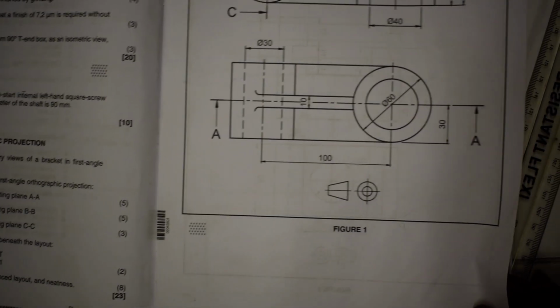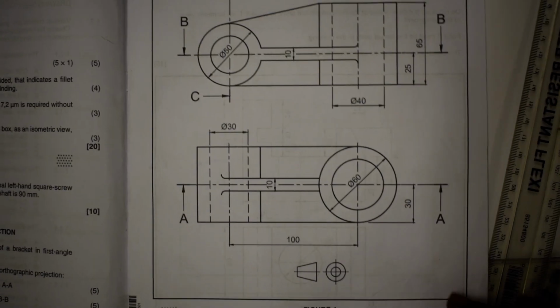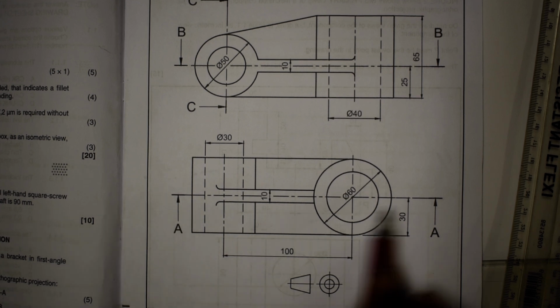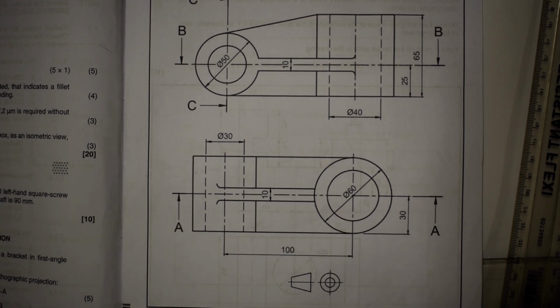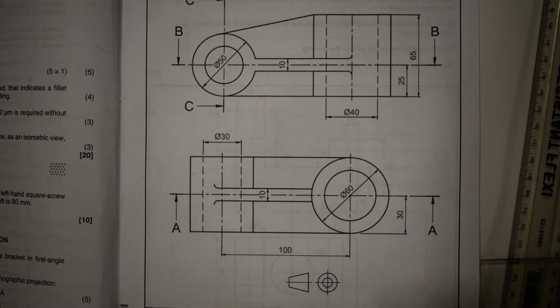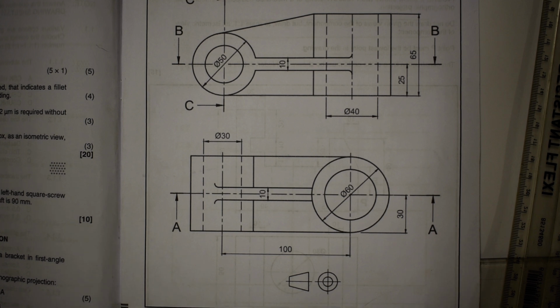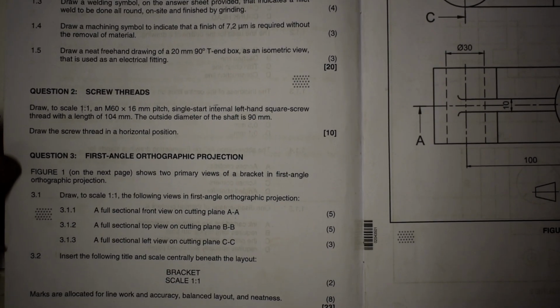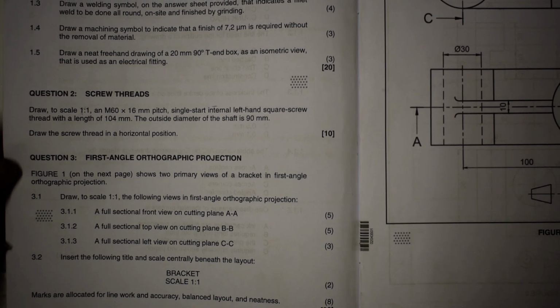When you look at the cutting plane AA, it is situated there by our top view. So it's talking about the front view. The law of sectioning in first angle, or even if it's straight, is that we draw what is being pointed at by the arrow. You understand? Whatever is beyond our cutting plane, we consider as an offcut. You get it?